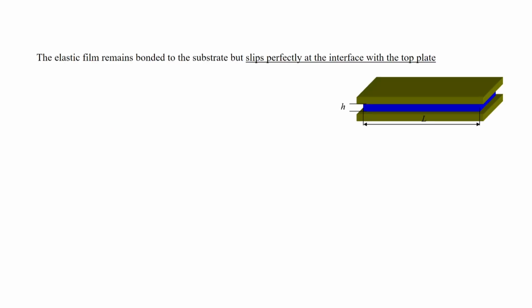So, very small actually. Now we will go to the next problem, in which case we consider that the film at the top surface has perfect slip. So, there is perfect slippage at the interface. Previously we were considering no slip, but now we will have perfect slippage, the other extreme of this spectrum. In that case, with perfect slippage, there is no shear stress that develops. Let us say sigma xz, at z equal to h, is equal to 0. So, that is the boundary condition that we need to apply over here.